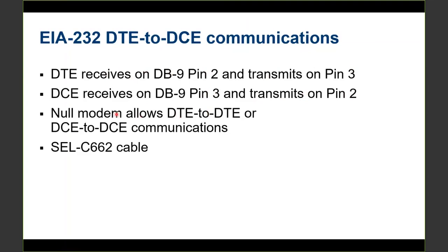And when I say that, this term null modem, if you ever hear this, we're not talking about a communications modem type of device. We're talking a null modem cable usually refers to a cable that basically, pin 2 on one side is connected to pin 3 on the other, and vice versa. And pin 5 is connected straight across, and then usually pin 7 and 8 are both traded.